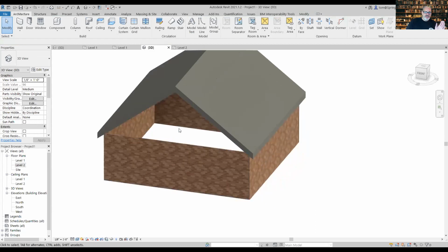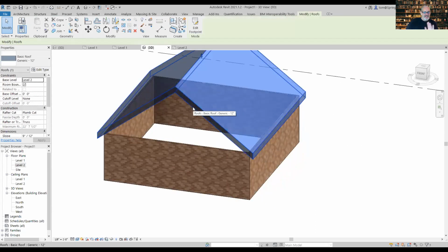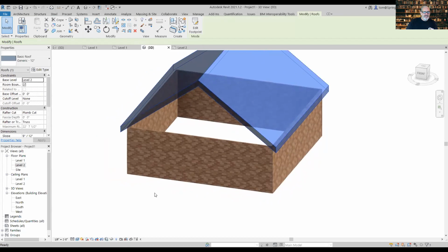And we talked about this. When I have this roof right here, I can select the roof, and when I select the roof, I can then set a roof pitch. Your roof pitch is defined. If you're not familiar with how roofs are defined, roofs are defined with what is called rise to run. In other words, it basically is like a fraction. So how many inches does it rise over a foot?